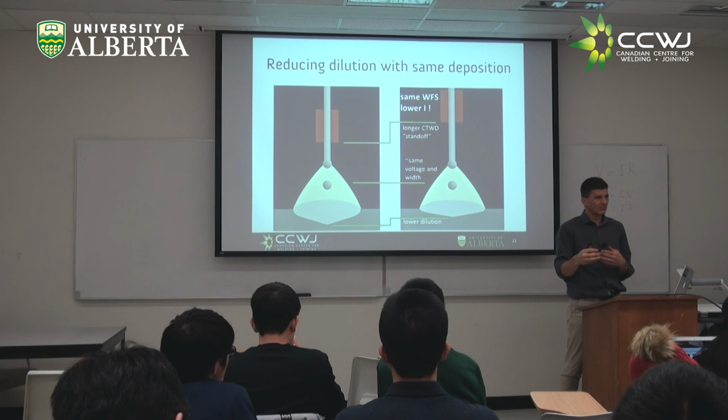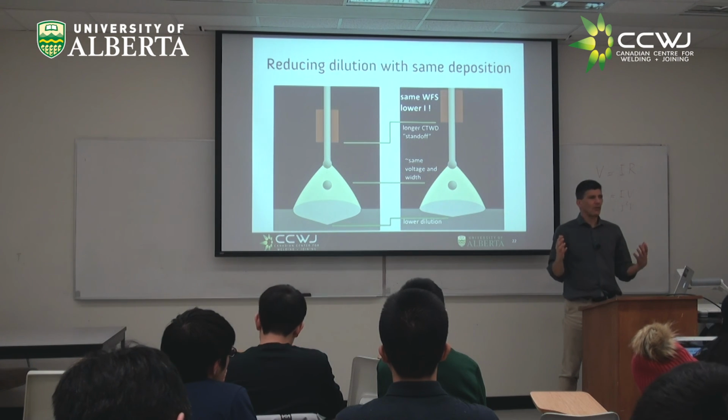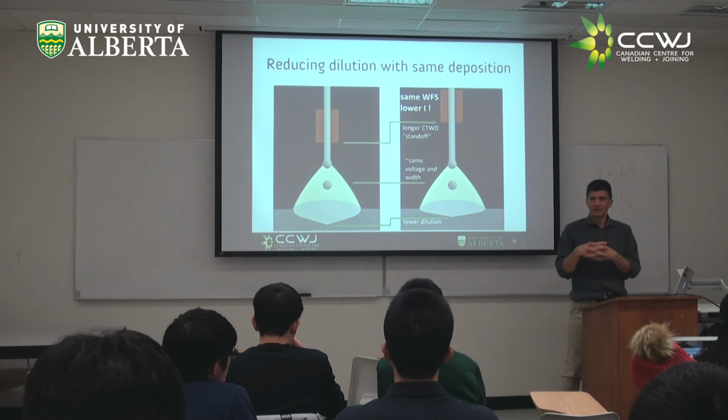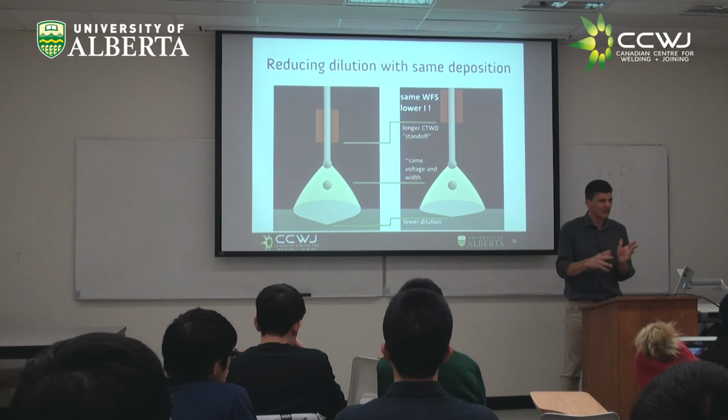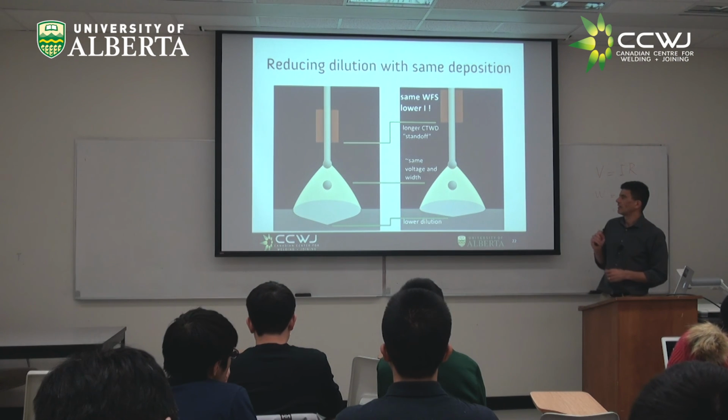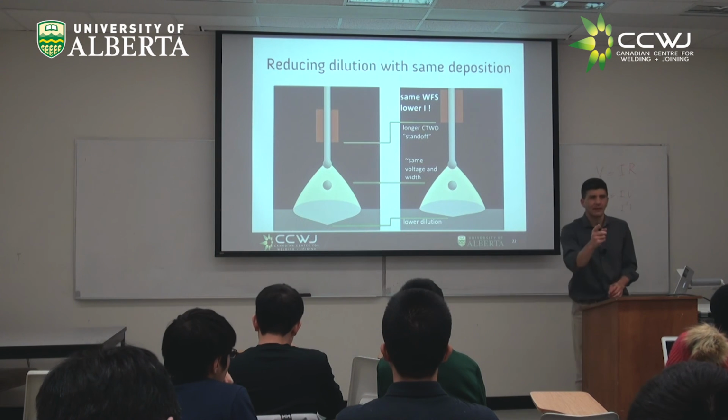Does the wire feed speed stay the same? The wire feed speed is set. When you do an overlay, you move at a certain speed and you put down so much wire, and they go together. You cannot change them because all of a sudden your deposit is going to be different. We're going to have a session on that too. Please think about this.